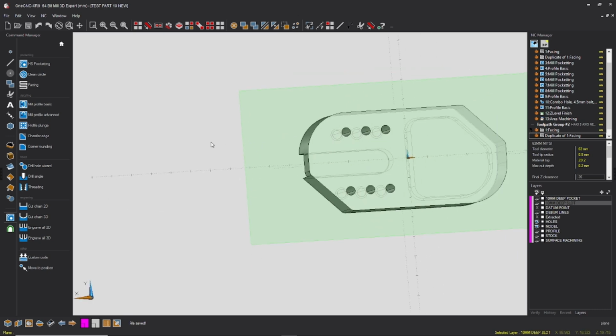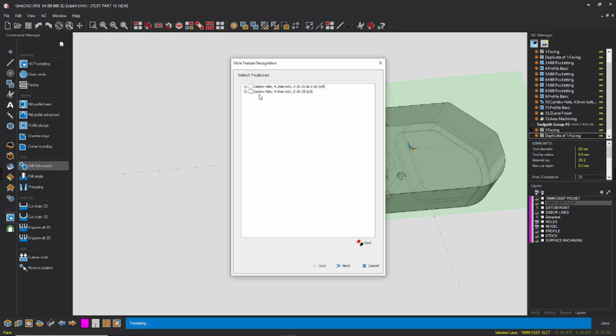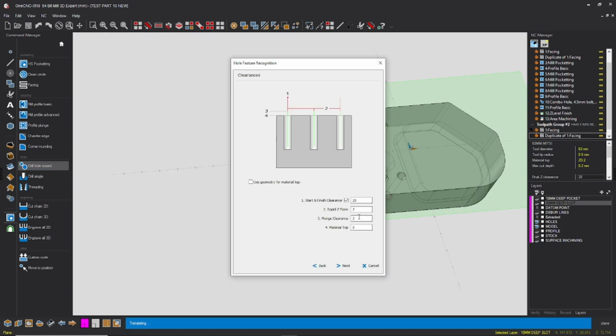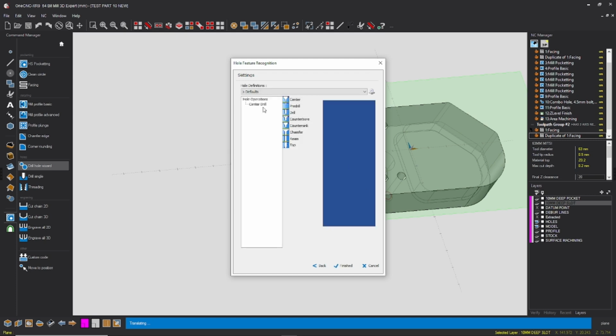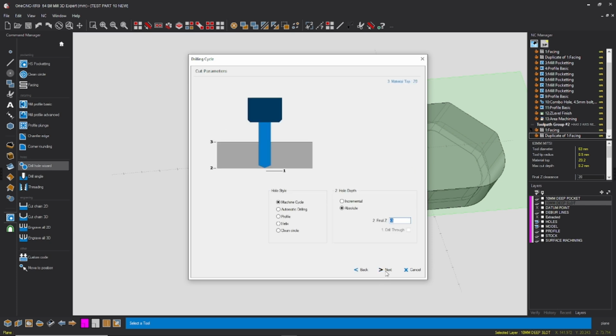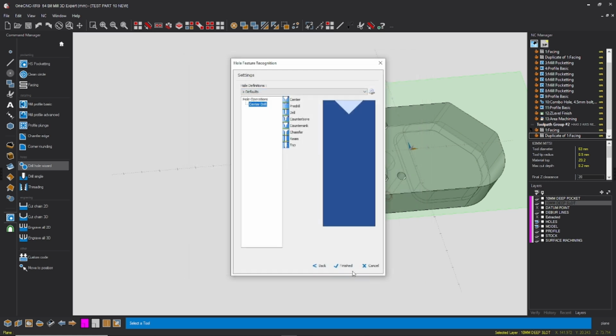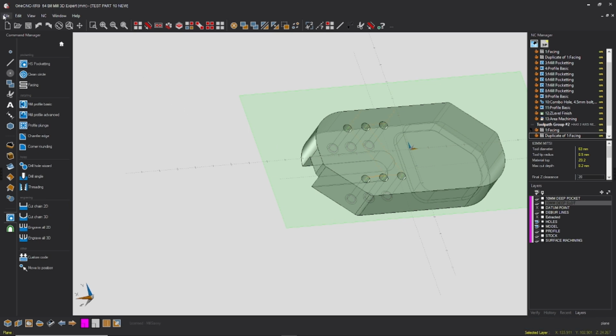Turn that off. Right, so the holes are down here, doesn't matter. Drill wizard, let's grab them holes. All this is fine. Grab our center drill, double click into our center drill, change that to G55. It's going to remember everything we've used from G54. So look, 3mm the same, but there is no countersink this side. So let's go 2.25 for half of 4.5. Click finish, click save. Now what we'll do is we'll go back up to here, make this our active group.